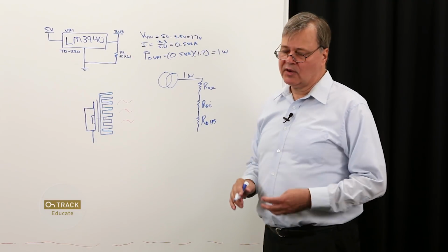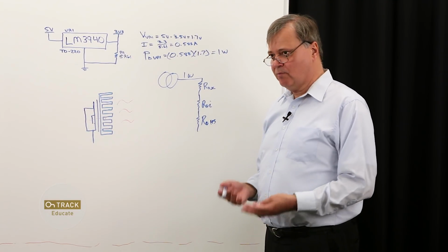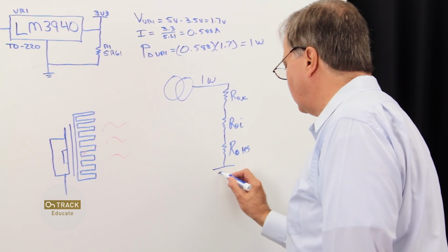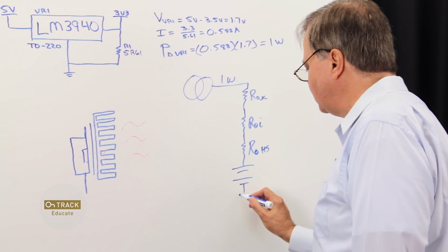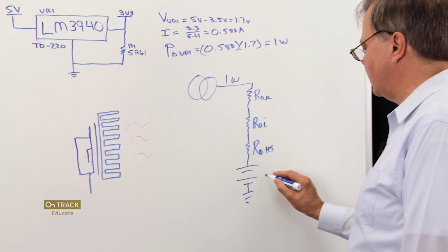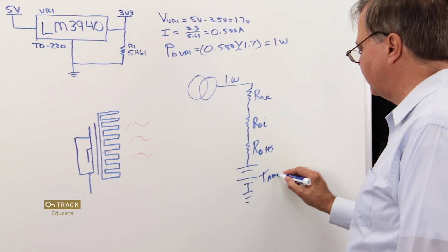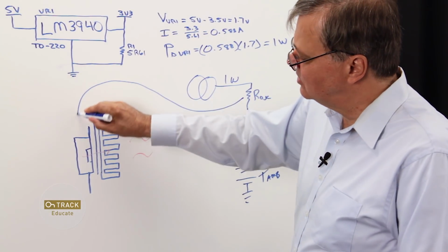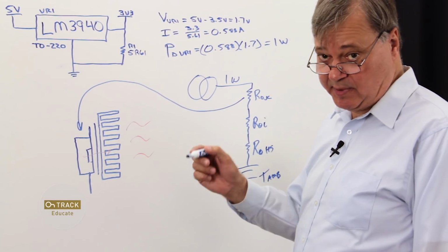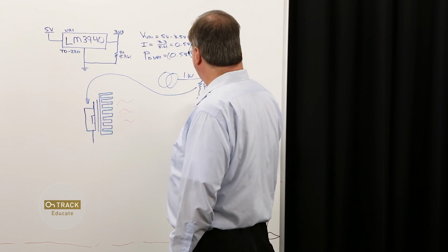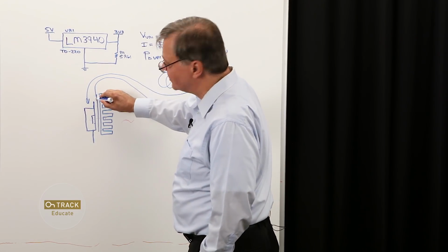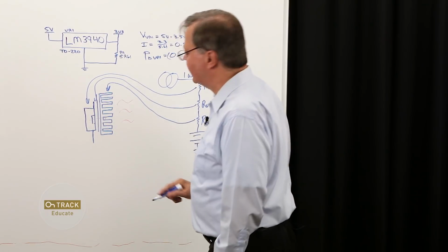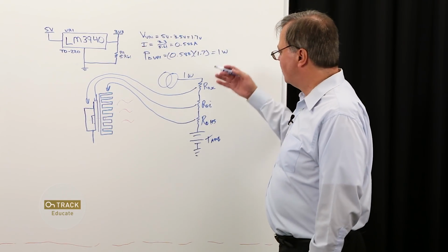And then you'll remember that we used a voltage source to model our ambient temperature that is biasing us up to an operating point. So I'll represent my ambient temperature with a voltage source, and this represents T ambient. So we've got our junction to case thermal resistance for our semiconductor device, then our thermal resistance for our interface material, okay? And then the thermal resistance of our heatsink to ambient temperature. And this is what we're going to be looking at.